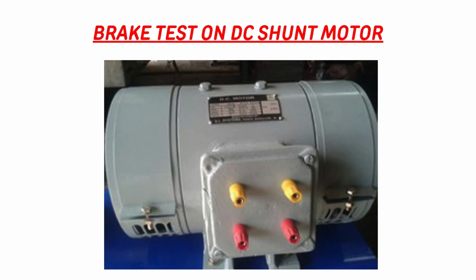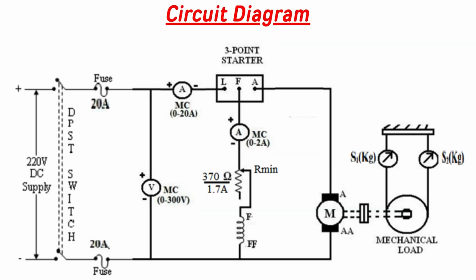Brake test on DC shunt motor. The circuit diagram consists of a 220 volts DC supply. Now, to obtain a 220 volts DC supply, normally we may use a rectifier which will convert a three-phase AC supply to a 220 volts DC supply, which is connected to a DPST switch.